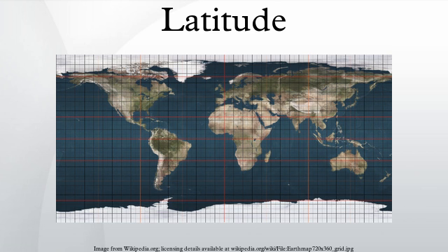the Earth. Spherical polar coordinates. The geocentric latitude is the complement of the polar angle θ in conventional spherical polar coordinates, in which the coordinates of a point are (r, θ, λ), where r is the distance of P from the center O, θ is the angle between the radius vector and the polar axis, and λ is longitude. Since the normal at a general point on the ellipsoid does not pass through the center, it is clear that points on the normal, which all have the same geodetic latitude, will have differing geocentric latitudes. Spherical polar coordinate systems are used in the analysis of the gravity field.